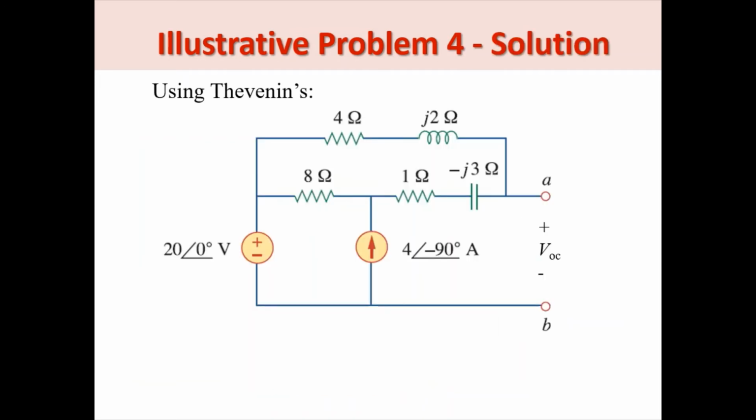So therefore, first we detach the circuit that involves the part where the current flows, where I sub naught flows. So we detach that and we determine the open circuit voltage across the open terminals. And let's use here mesh analysis. So we assume mesh current I sub 1 here and mesh current I sub 2.